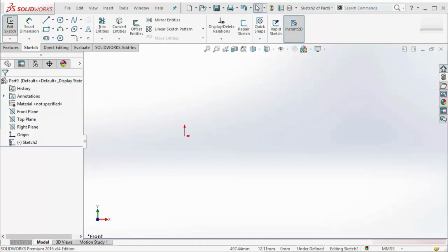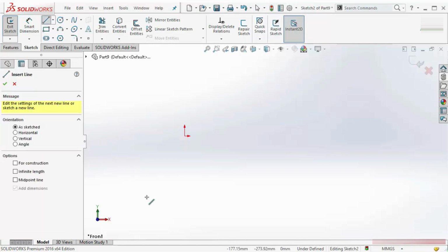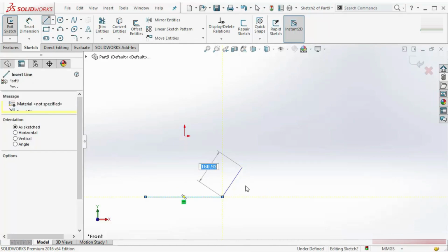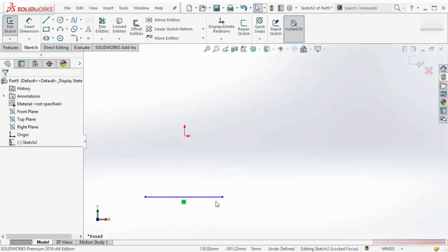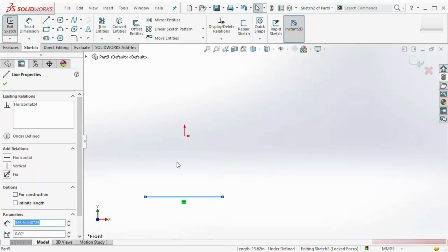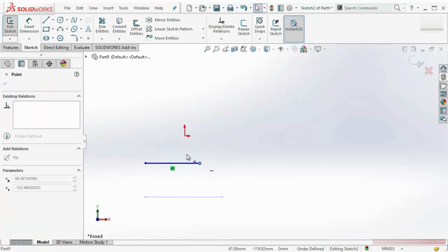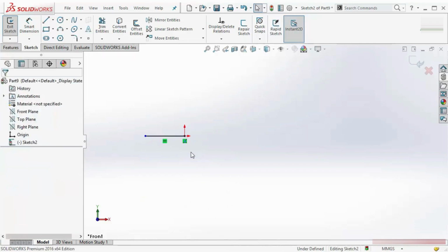In this lesson, I will show you how to define a sketch fully. Before I do that, let's say if I create a line, this line is blue now. If I select it again, this will be light blue. But if I move this to this point, you will see this is black. So this is changing. Now question is why this is changing? Why this is from blue to black? Well, when this is black, that means this sketch is partially defined.